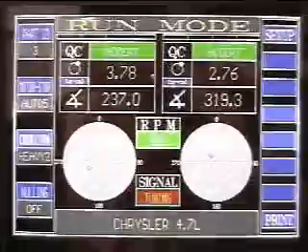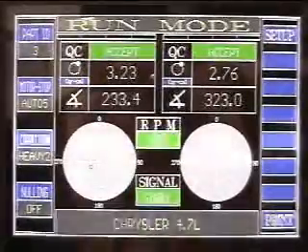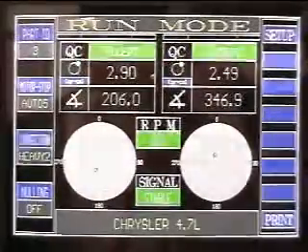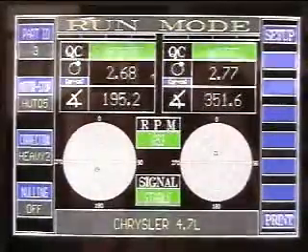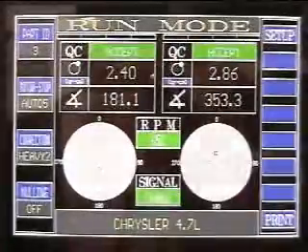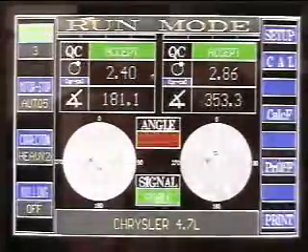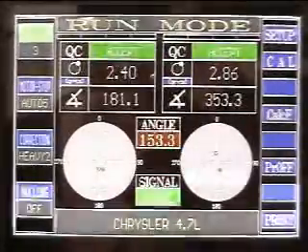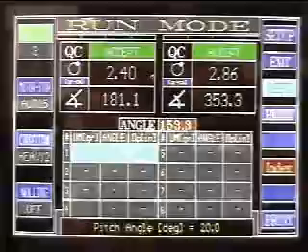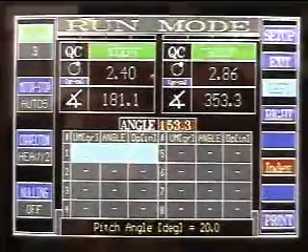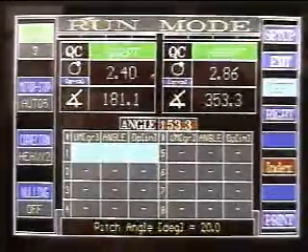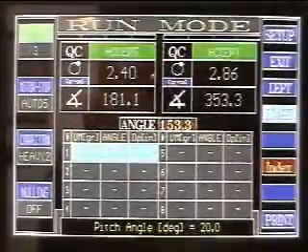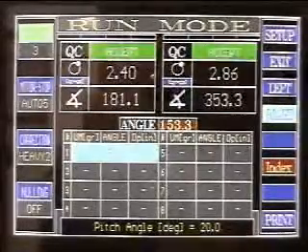Displayed here is a typical audit cycle. The part speed and transducer signal stability are monitored. Upon completion of the audit cycle, the correction screen is displayed. This screen indicates to the operator how many holes are to be drilled as well as angular locations. But before further information regarding the correction process, it is necessary to explain the part setup procedure.